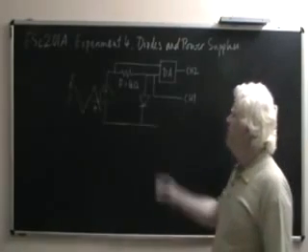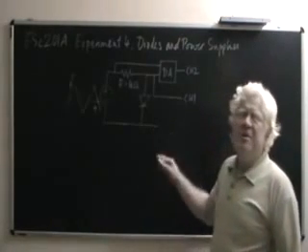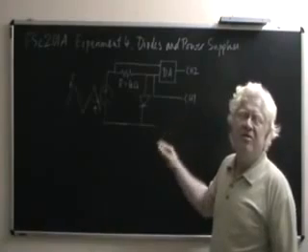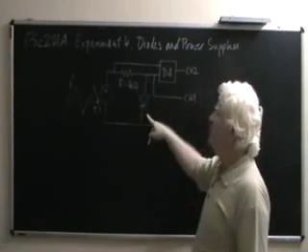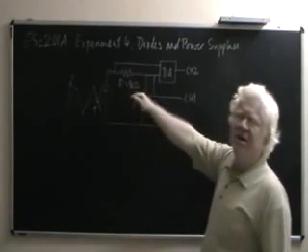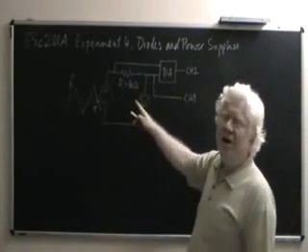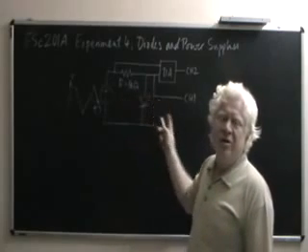So here is the circuit we use to carry out the experiment that determines the characteristic of the actual diode. Here is the actual diode under test in this place, and here is the resistor that I said you need to connect in series to measure the current that flows through the diode.